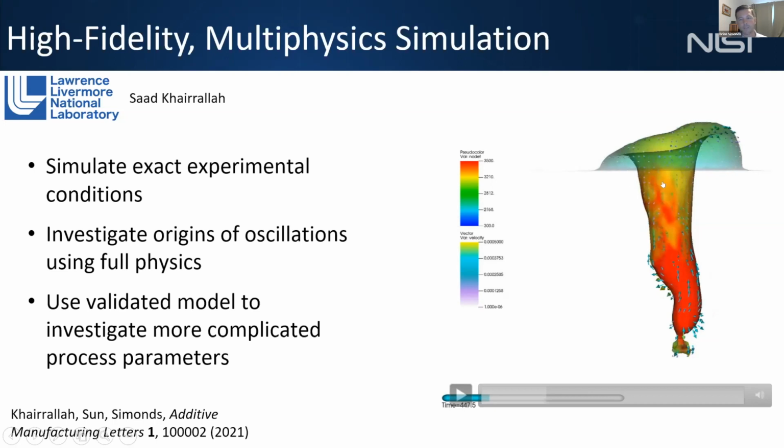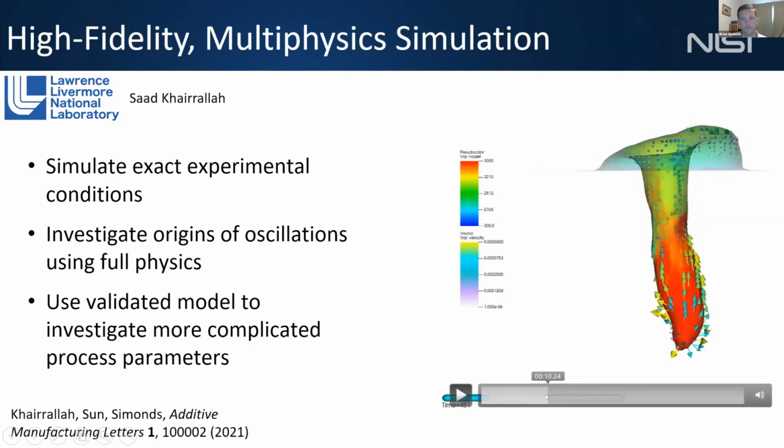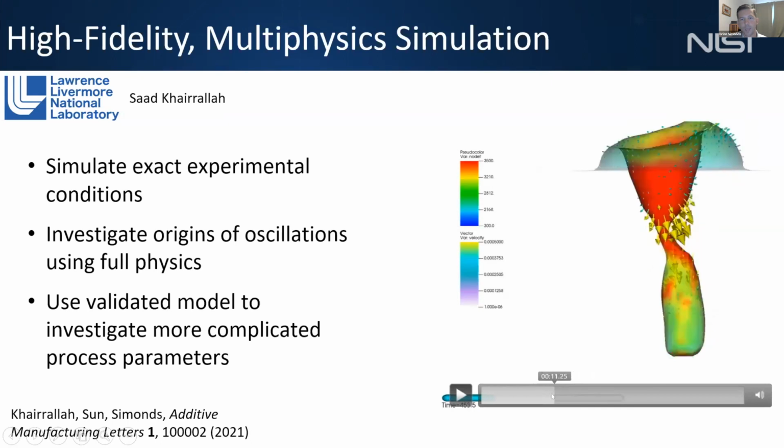So that starts to show up here in green. And when that happens in these materials, the surface tension starts to strengthen and leads to the necking of the opening that starts to occlude it. So if you continue this a little farther, you see that this cooled region at the top is starting to close down. And when that happens, light can no longer get to the bottom of the keyhole, which then starts to cool.